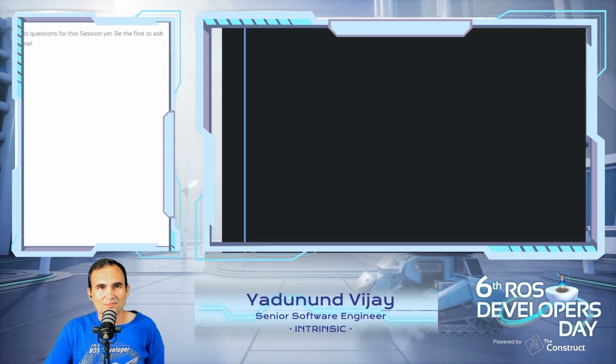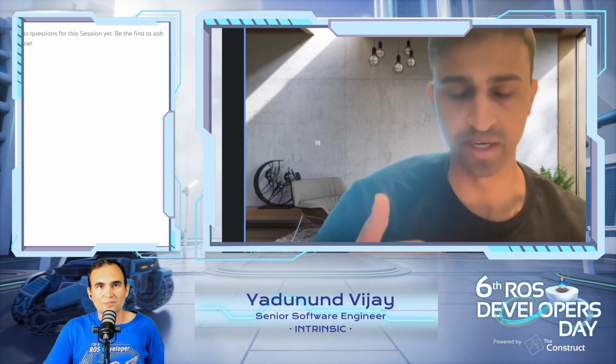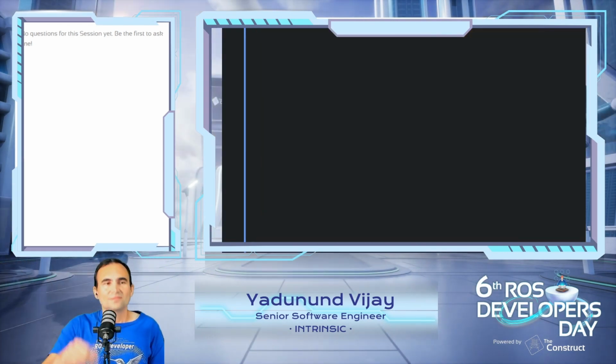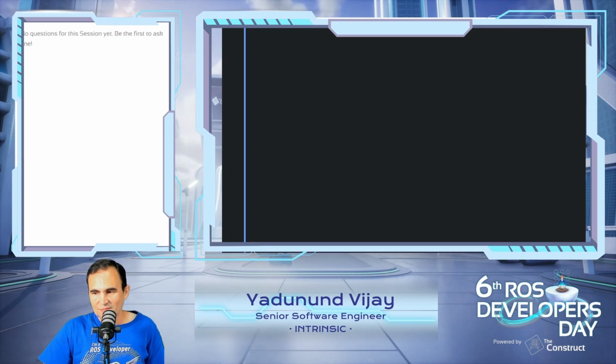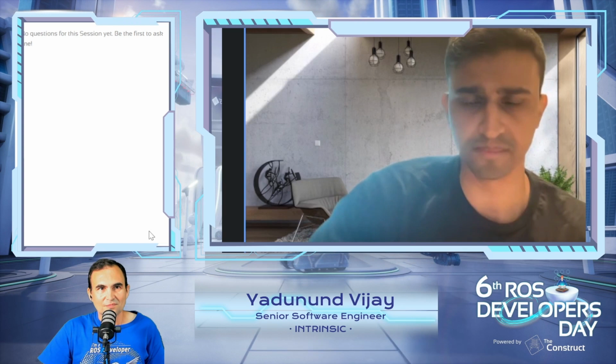So for example, you have the MiR robot, it uses ROS internally, but users can only interface with the robot through a REST API or maybe a WebSocket API. And that's totally okay. The point is you'll be able to write your fleet adapter such that whatever protocol your robot uses to communicate, or to ask it to move somewhere, ask it to stop, get information from the robot, you can implement your adapter such that it talks to the robot using that specific protocol.